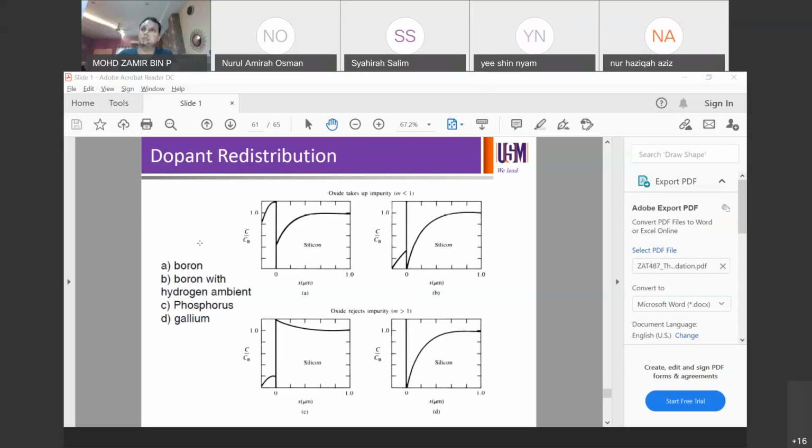If you talk about the real wafer process, this is going to happen in the diffusion and oxidation process. Typically, it's under one department. If you talk about Siltera, I'm not sure about other fabs. In Siltera, diffusion and oxidation, both processes are controlled under one department. So if you are the process engineer for oxidation, you're going to look into all this stuff, right? If your device or oxide has a problem, poor quality or something, or the dopant distribution is not as intended, this is the thing that you have to know, right?